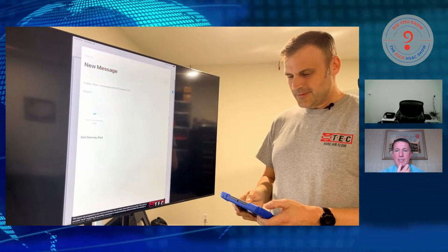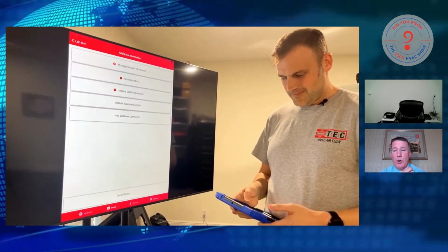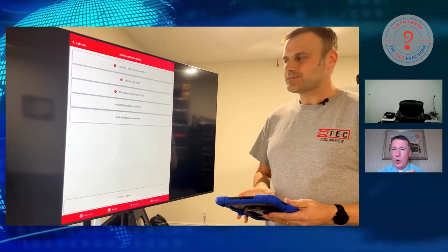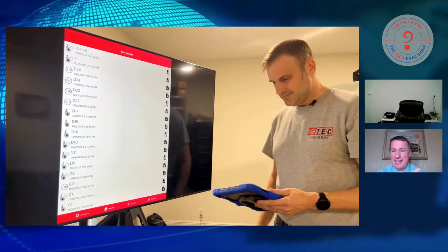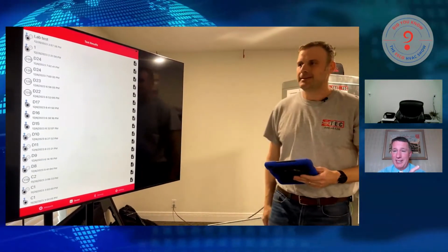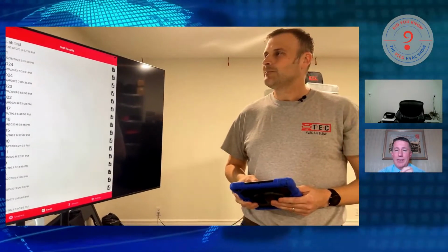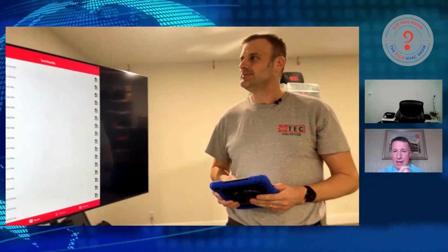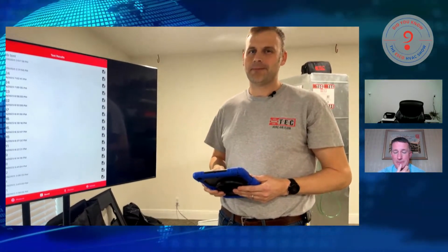Yep. I mean, think about that job where you're going out to evaluate a call, hey, I have poor airflow. And even if it's just a coil cleaning and a technician does a 5-minute pre-test, get an idea what's going on, do a complete system clean check, clean coil, validate it with a second follow-up, you're showing how much of an improvement you have on the performance of that system and the airflow moving through that duct.